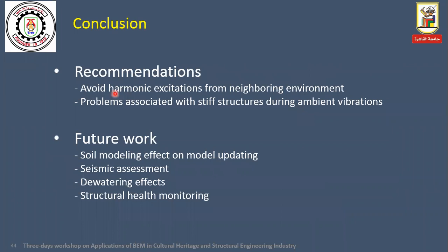The structure that we measured was very stiff, so the measurements of the vibration from just ambient vibration were also a big challenge. The best measurements we were able to pick up were when heavy trucks were passing by, so that we were able to excite the structure somehow with this ambient vibration.